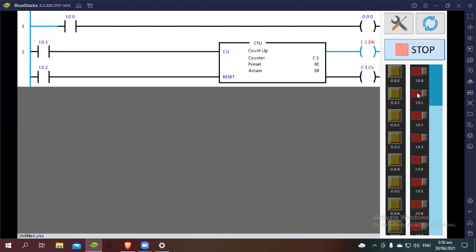The only thing that can change it back into a black or zero value is the application of the reset. It doesn't matter if the count input is held high or low. If reset is active, the count will never be considered valid, or it will not enter as an accumulated value.